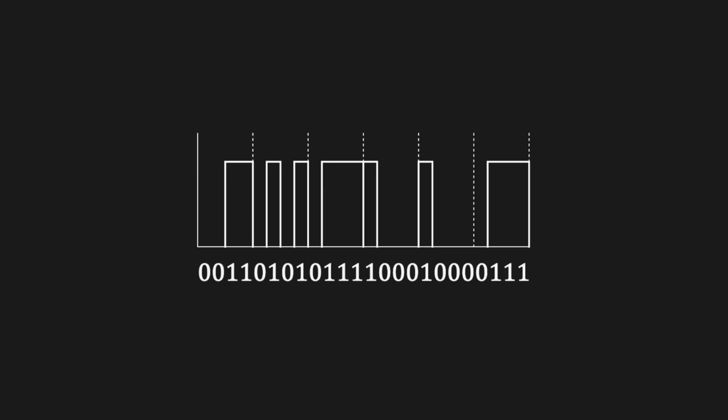Modulation is a way of encoding information so it can be sent or stored. The most common type is Pulse-Code Modulation, PCM, where an incoming analog signal is sampled, quantized, and encoded into digital form. In PCM, the strength, amplitude, of each sound sample is turned into a binary number, allowing computers to represent the sound with digital pulses. At playback, these binary codes are used to recreate the original analog waveform. Because PCM stores exact amplitude values, the signal can be reconstructed without loss.